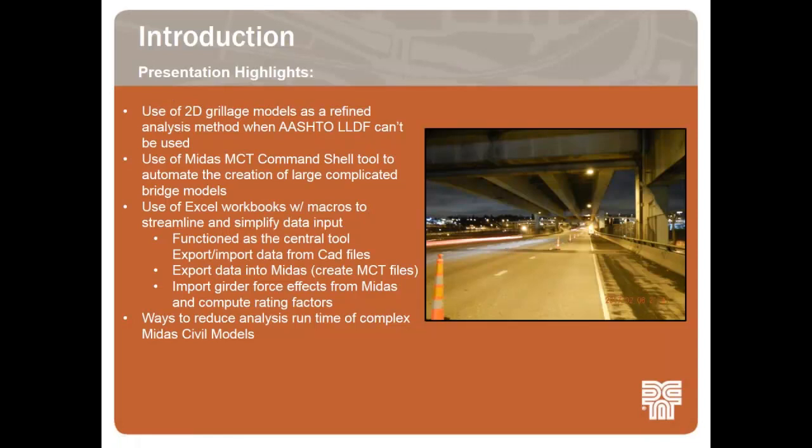Some of the highlights of my presentation will be how to use 2D grillage models as a refined analysis method when the AASHTO live load distribution factors can't be used, how the use of Midas MCT command shells can help automate the creation of large complicated bridge models, and then how you can use Excel workbooks with macros to streamline and simplify the data input.